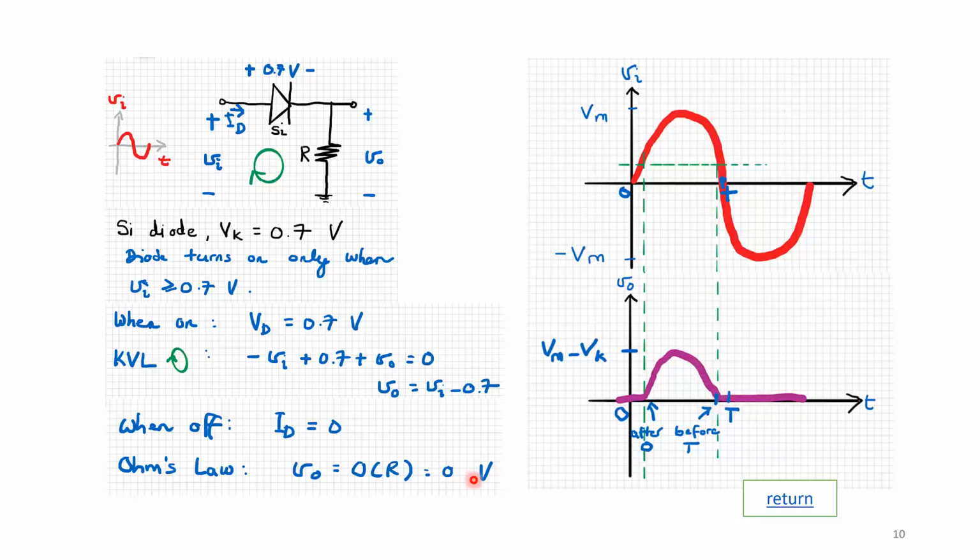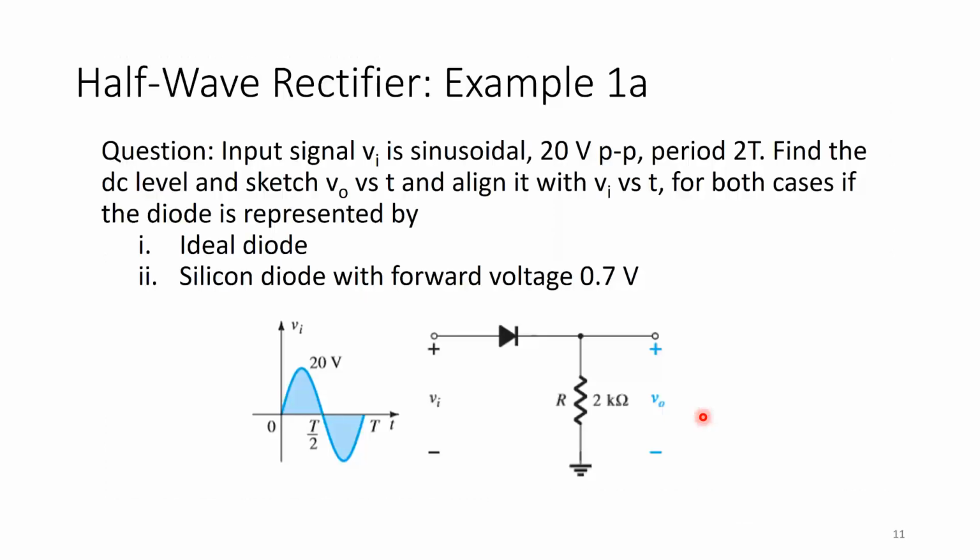Okay, which obeys here, because this diode would have turned off when V in is not strong enough, even though it is in the direction of positive current flow. When it is less than 0.7, it will turn off, and therefore you will find this difference between when it crosses from positive to negative in V in and in V out.